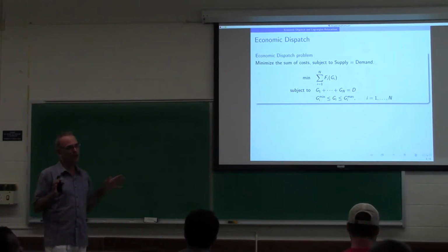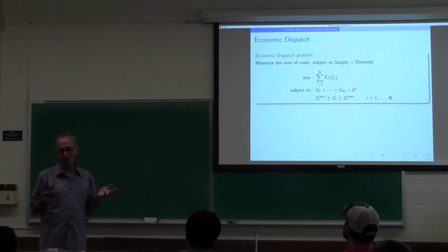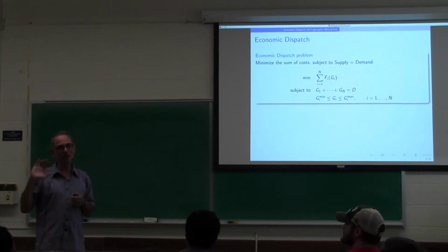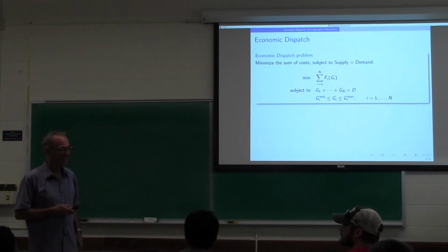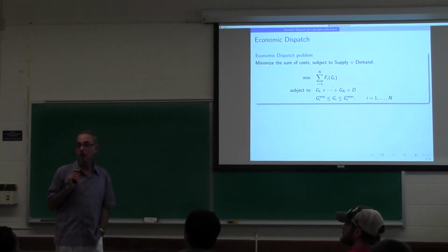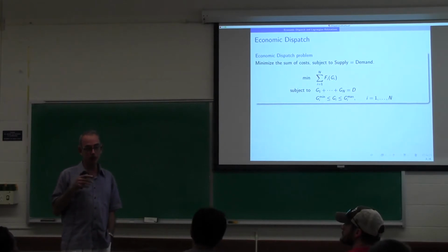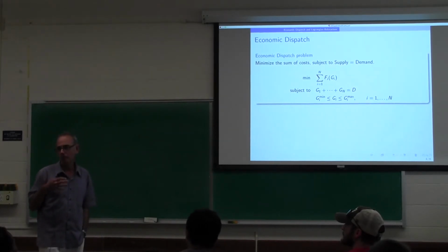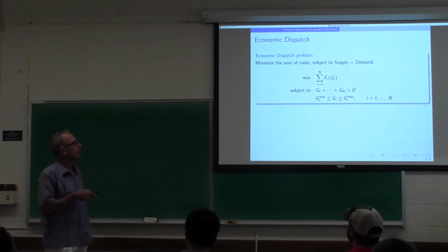I've got 100 generators, and I want 10 up, n equals 10. That's 100 choose 10 possibilities. It's a combinatorial nightmare, and you have to take a course in mixed integer programming. In industrial engineering, we have the best department in the world for that, so go over there. There are all sorts of specialized algorithms for solving that, but it's not the hardest problem. The balancing authorities, like the ISOs, don't find any trouble solving the unit commitment problem, even though it seems quite difficult. This they find much more difficult.